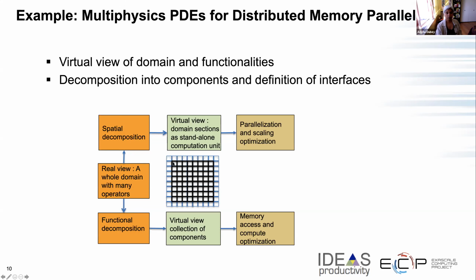So the black cells here are the cells that are updated by the physics operator, and the blue cells are the ones that are obtained from neighboring components of the domain or the physical boundary, and they act as ghost cells. We're all very familiar with this concept of ghost cells, right?